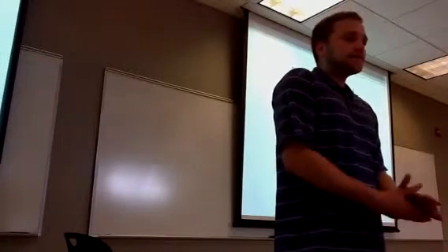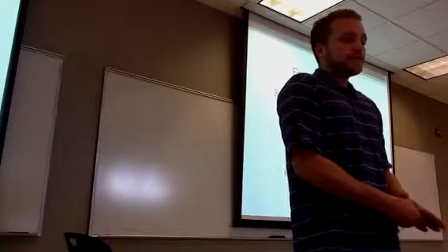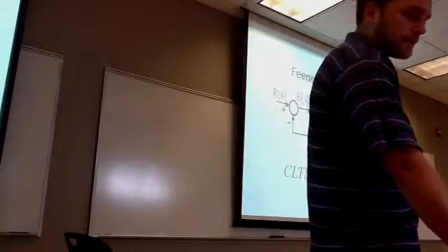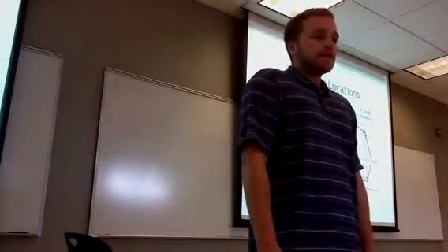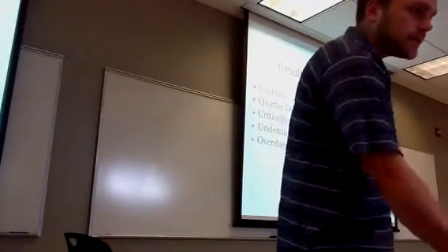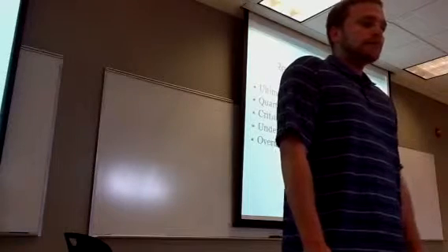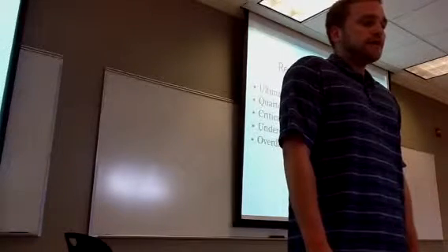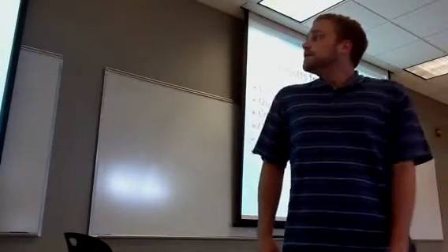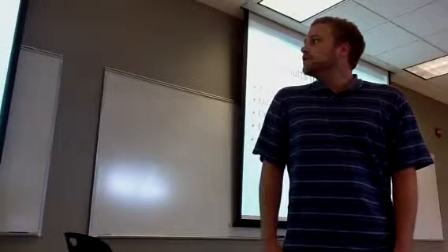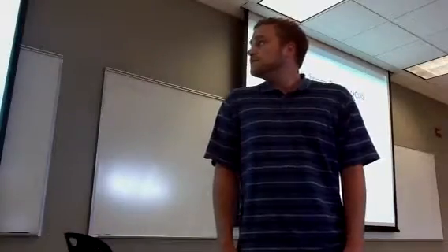Here's the feedback control, just a schematic of it. And here are the parameter locations for our root locus plot, which gave us that the ultimate controller gain was 0.47% per RPM. The quarter decay is 0.24. The critical damping is 0.05, and it's underdamped between 0.05 and 0.47% per RPM, and overdamped between 0 and 0.05% per RPM.